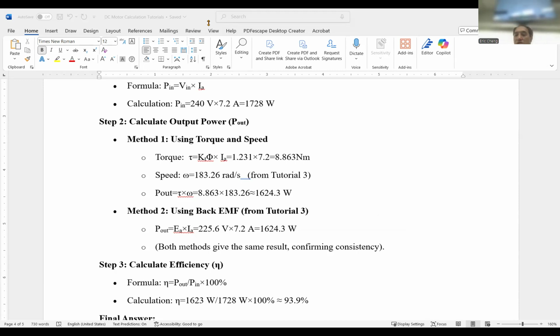So you can see the ripple is 1.8 ampere. The inductor current, once 120 volts is applied to it, will go up by 1.8. So the peak to peak ripple current is equal to this 1.8 amp. You can see it in here, the ripple is 1.8 amp.